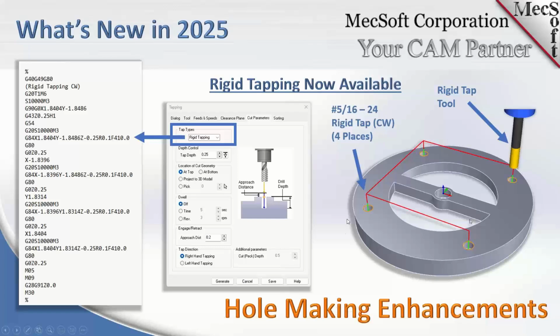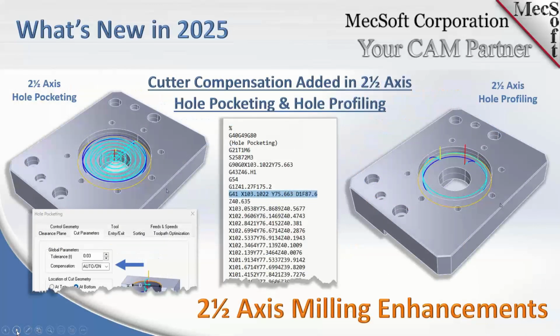Let's just recap there. In hole making, there are now multiple options for tapping, and I'll show you that on this part. You have a rigid tap, which is the new method, and then your previous method, which was a regular tap, and we'll show you that. Okay, so we're going to start with 2.5-axis milling.